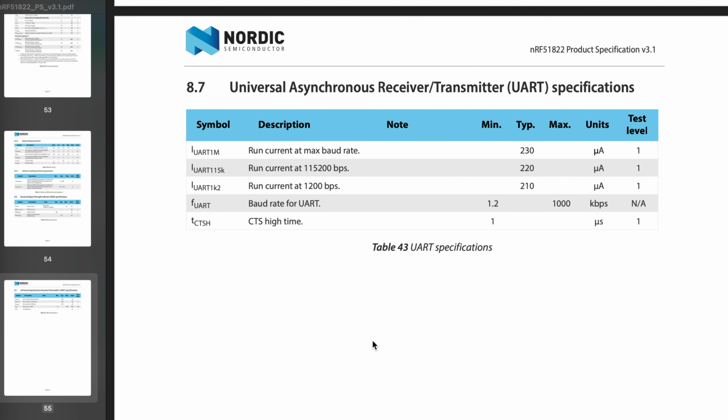Another important parameter that we will have to consider for our design is the speed at which the microbit will communicate to our computer. The microbit communicates with the computer using a USB as a serial port, and the speed is 115,200 bits per second.